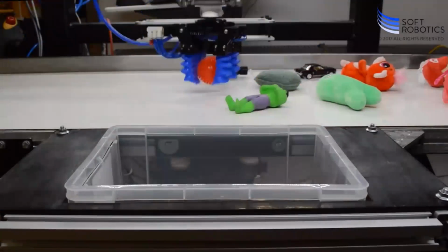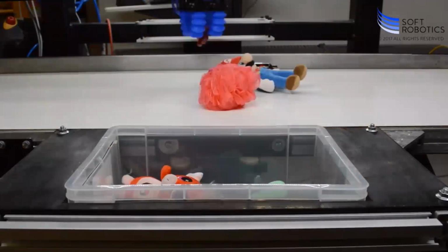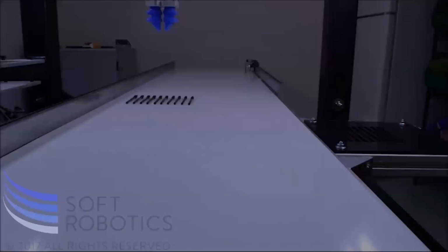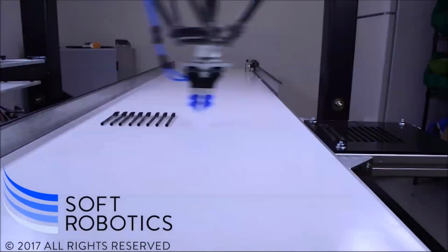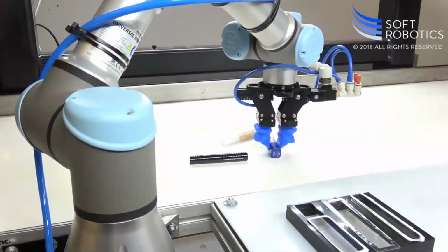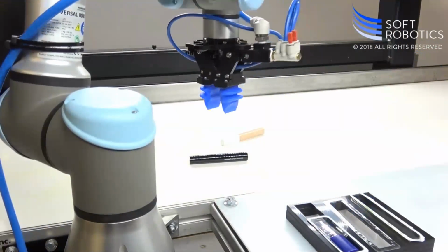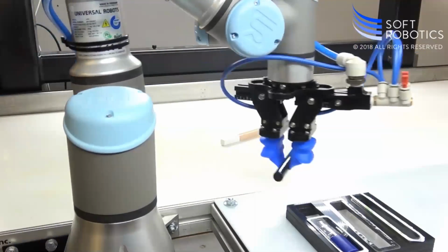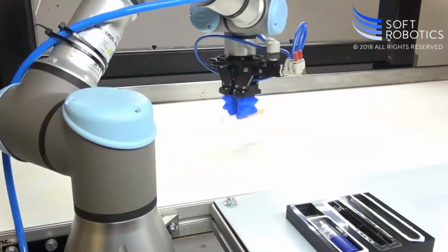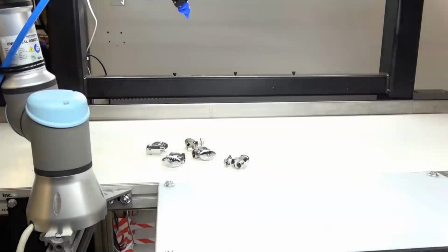Now these are powered by pneumatics, so they've got two different versions of it, so you can run it off your own pneumatic system, or they have a control box with a motor in it that creates its own vacuum. Essentially, they pull a vacuum to expand the piece and then put it under force to contract the fingers. The range determines how large the fingers open and close, and how much pressure you put on determines the force. They've got quite a modular design as well. You can see they have the two finger setup there with the short fingers, or they can have a lot longer fingers and then up to 10 or 12 different fingers going on.